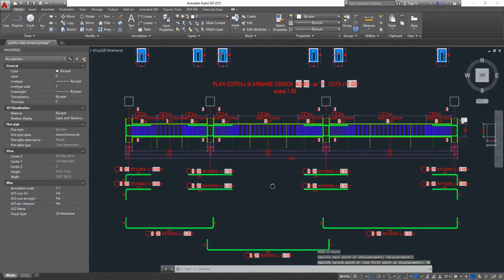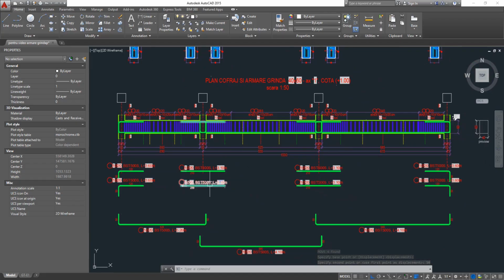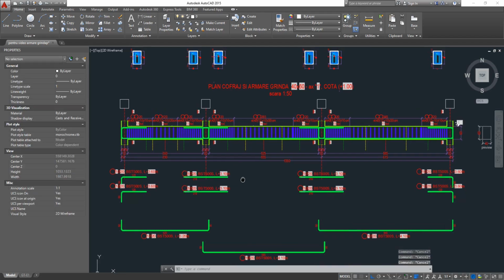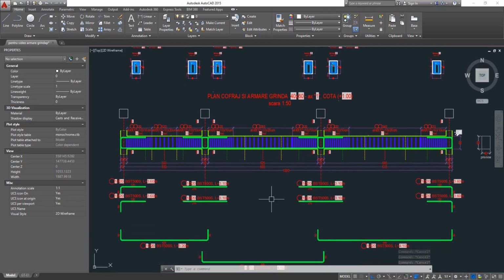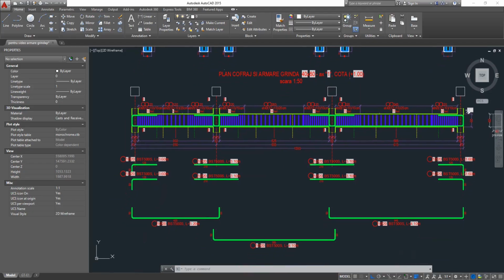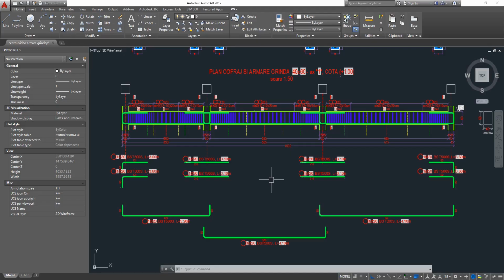So this was just a method for me to actually double the rebar, but also make them distinct from the first layer. So we're not talking about a first and second layer. We're talking about the same top layer for the beam, but we're going to use different diameters. So now, what can we do? We can actually change the shape or the diameter of each bar as we please. So for the time being, we're going to leave down the whole carcasses as you've seen. We're just going to change the diameters.